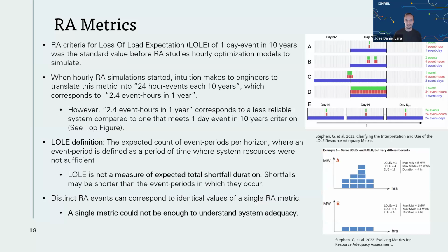So let's go to the next slide. Now I'm going to leave it with Sebastian to discuss some of the most important metrics when it comes to deciding if your system is resource adequate or not. Thank you, Jose. One final remark about resource adequacy metrics is that traditionally resource adequacy criteria used a loss of load expectation of 1 day event in 10 years as the standard benchmark. We need to be aware that this was established before hourly resource adequacy simulation models became common.